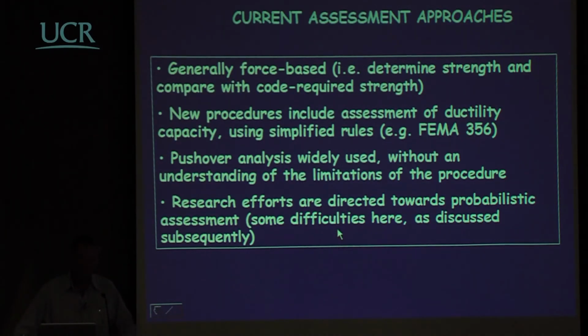So let's look first at a bit of background associated with assessment of existing structures. Generally, this tends to be force-based. In other words, we determine the strength of a building itself, typically in terms of the base shear capacity, and compare this with code required strength and come up with some capacity demand ratio. New procedures include assessment of ductility capacity using simplified rules, for example, FEMA 356. Pushover analysis is widely used without an understanding of the limitations of this procedure, because of course it doesn't represent the higher modes at all.